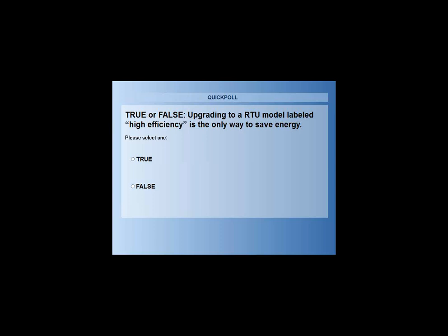It's a great question, Jeff. So the energy codes, I don't have the code on my computer to bring it up right now, but the energy codes are not a new construction thing. The energy codes, specifically the IECC, spell out in there that this applies not only to new construction, but also to renovations, alterations, additions, replacements, and repairs, right? So as soon as you change something in the building, you've got to bring that thing up to code.